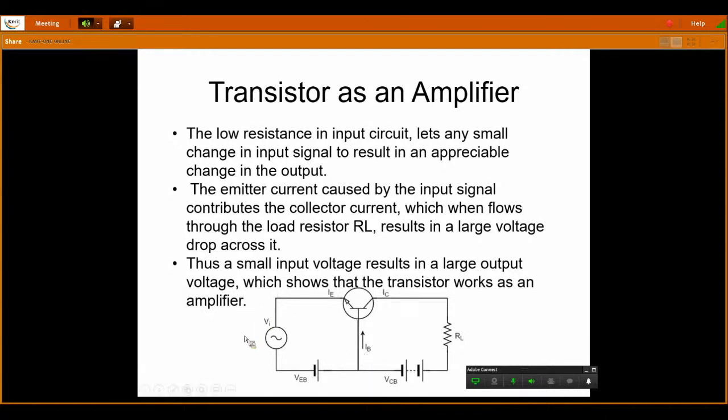Now by introducing an AC signal at the input of your transistor in a common base configuration, the input terminal is the emitter. Hence, the AC signal which is to be amplified must be applied to the input terminal, so we connected it to the emitter. The positive terminal is connected. Your AC signal, the alternating current signal, is the weak signal strength voltage applied to the emitter terminal, the input terminal of your common base.